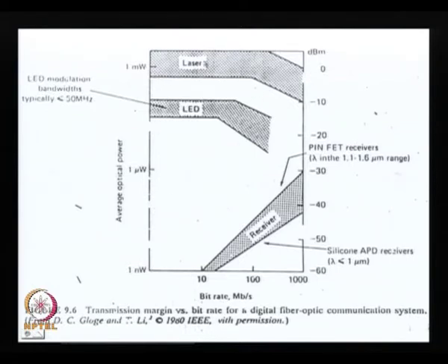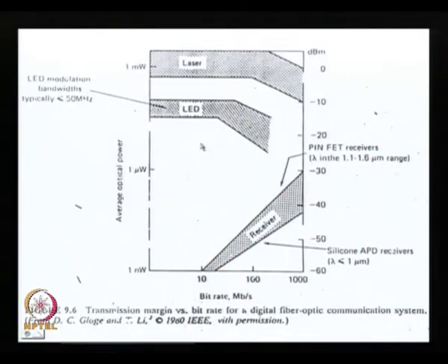That means even if the laser may supply the power, as soon as the data rate becomes higher and higher, the effective power supplied by the laser becomes smaller and smaller. And the same is true for LEDs, because all these are PN junctions, which are essentially low frequency filters.